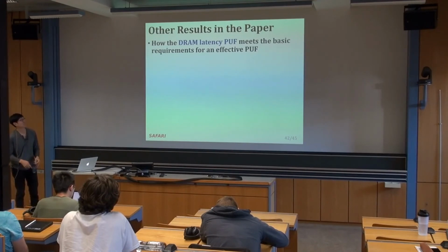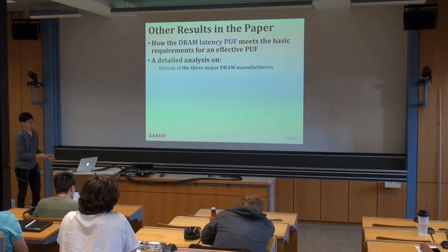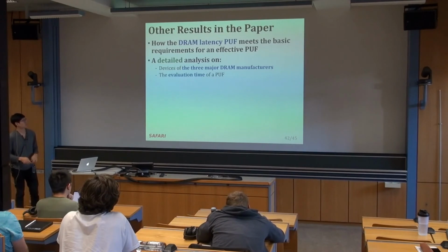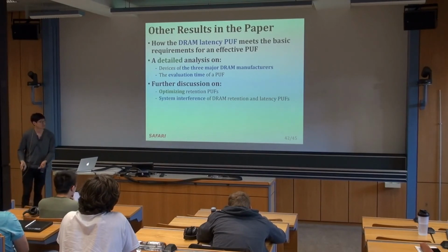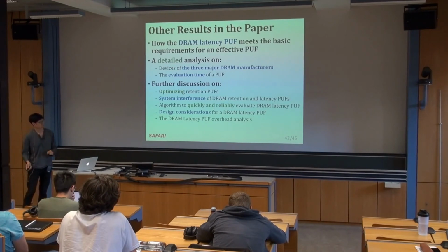And there are other results in the paper that we don't discuss in this talk, but they include how the DRAM latency PUF meets the basic requirements for an effective PUF, a detailed analysis on devices of the 3 major DRAM manufacturers, the evaluation time of a PUF, and further discussion on optimizing retention PUFs, system interference of DRAM retention and latency PUFs, an algorithm to quickly evaluate the DRAM latency PUF, and design considerations for a DRAM latency PUF. Also, the DRAM latency PUF overhead analysis.